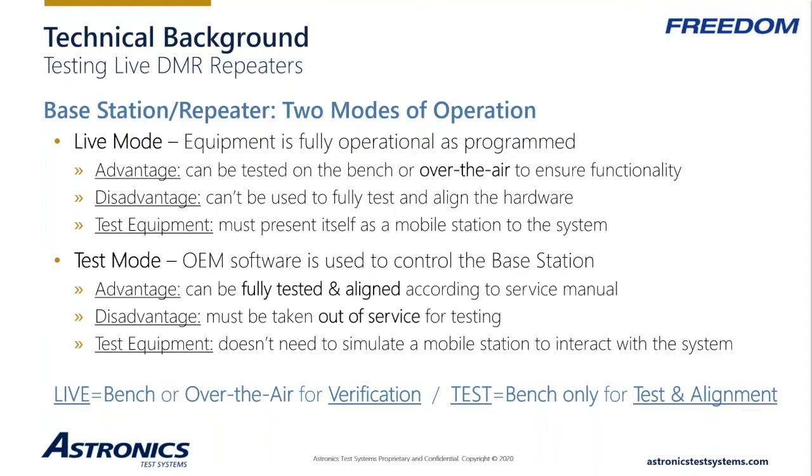Over the air testing can verify that the repeater is functioning as a repeater, but may not be able to determine how well it is able to perform this job. For example, accurate power output and receiver sensitivity measurements may not be possible unless the base station is put into test mode. And that's the other way of testing the repeater.